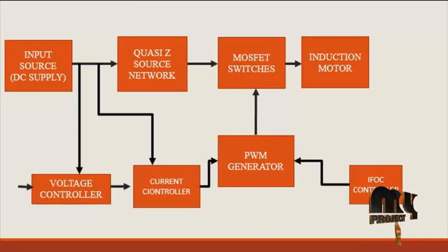The traditional ASD system is based on a VSI, which consists of a diode rectifier front end, DC link capacitor and inverter bridge. It suffers from common limitations and problems, such as the obtainable output voltage being limited far below the input line voltage. Voltage sag can interrupt an ASD system and shut down circuits, loads and processes, and the performance and reliability are compromised by the VSI structure.